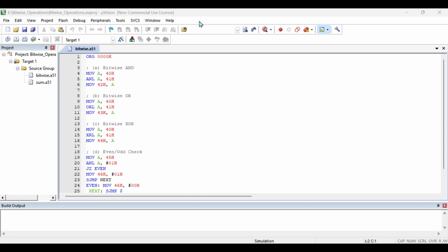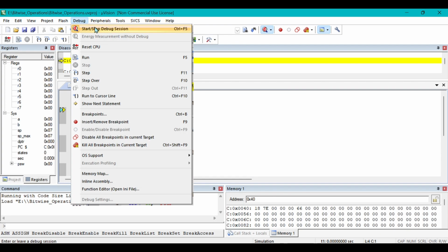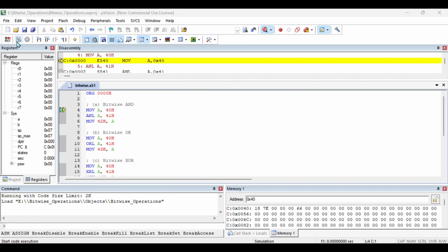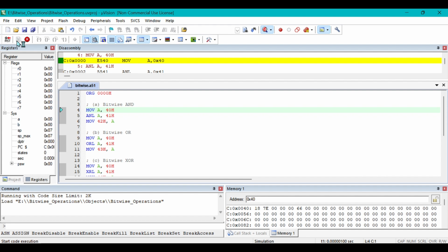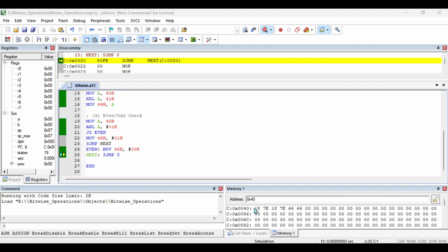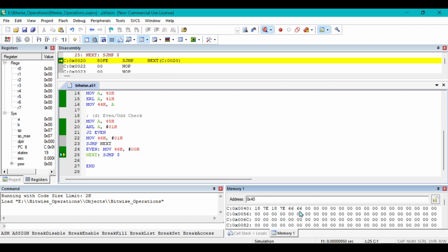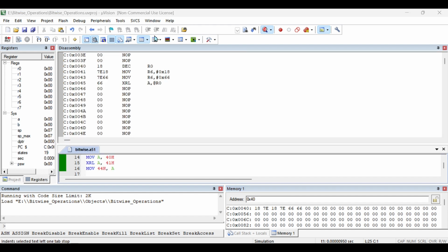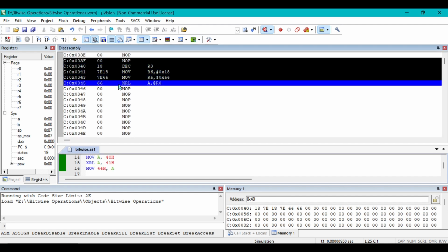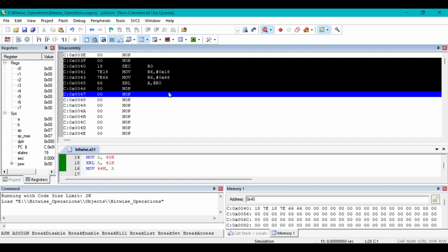The LSB of 66H is 0, therefore the operation result is 00H. The simulation confirms that 00H is stored in the result address. Since a 0 result signifies that the LSB was 0, this confirms the sensor reading of 66H is even. This successfully validates all the bitwise logic and data manipulation for this embedded application.